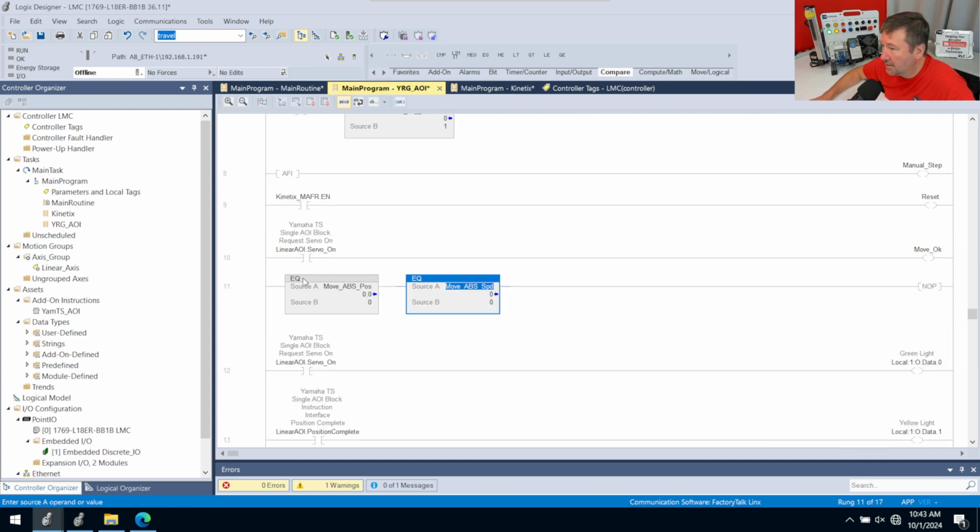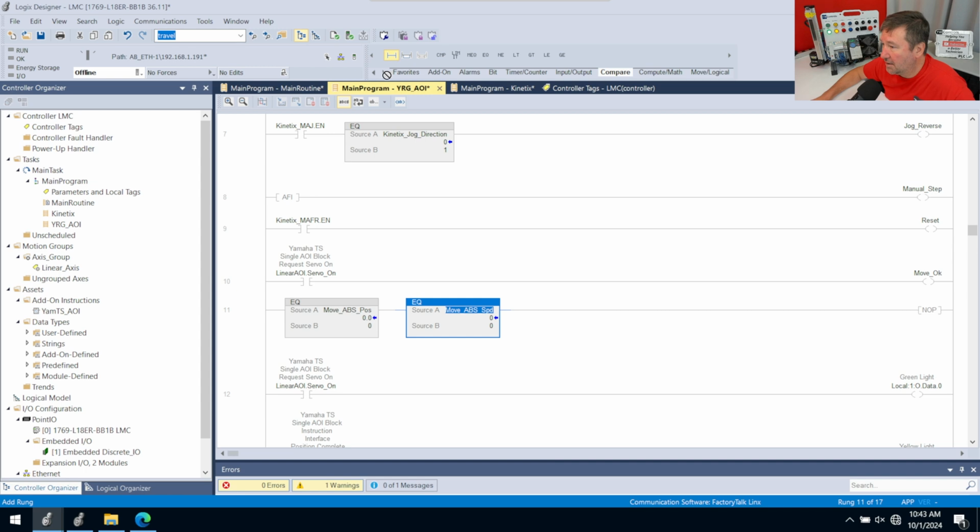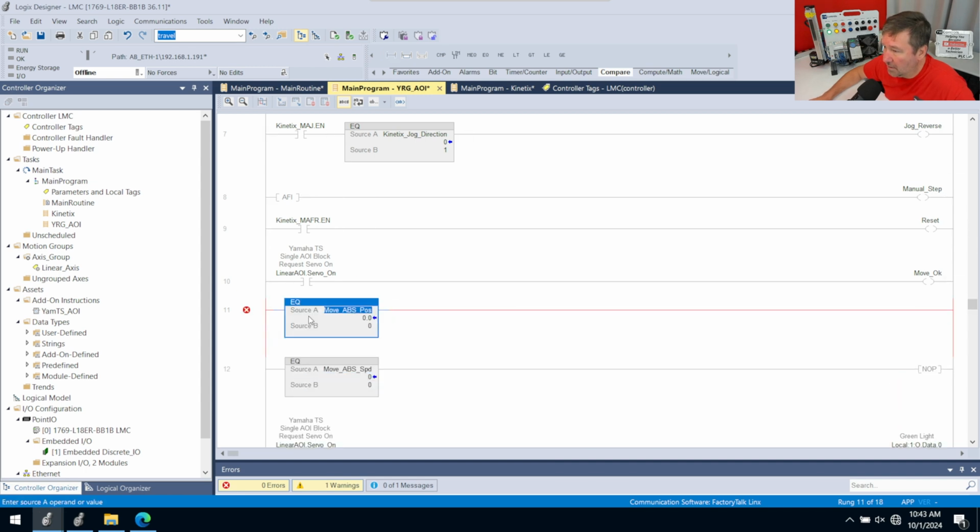As we're going to need to split these up. Yeah, let's bring a new rung down, because for now we are making our absolute speed 100. So I am going to drop that down and just put 100 into our absolute speed and change this to an MOV instruction. And we can take that out now. And down here though, this will be an MOV instruction as well.